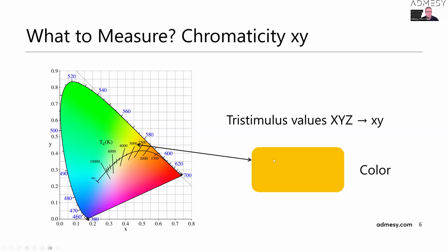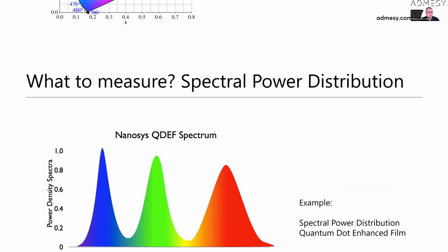And then describe a specific color. And you measure, for example, red, green, blue, white, and black, several gray steps typically, but for some applications you might measure, for example, even up to 5,000 color patches, for example, to calibrate a display, a TV. That is an application where they use a really large set of colors. And that means you also need to be able to measure very fast to make all those measurements in a reasonable time.